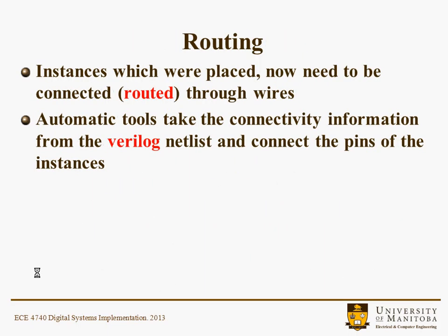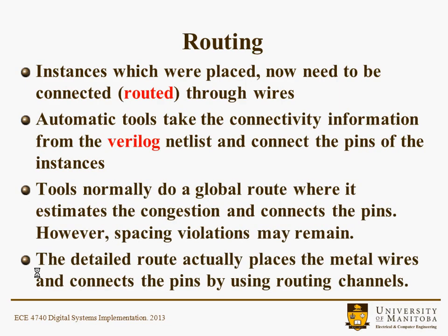Routing is another part of the ASIC design. Once the instances are placed, you need to be able to connect them up through wires. Automatic tools take the connectivity information from, in this case, a Verilog netlist, and connect the pins of the instances. Those instances are modules or gates or standard cells, and routing is basically responsible for connecting those up. Tools normally do a global route where it estimates congestion and connects the pins, and then a detailed route usually takes place to place metal wires that connect up the pins using routing channels, or at least that's one means of doing it.